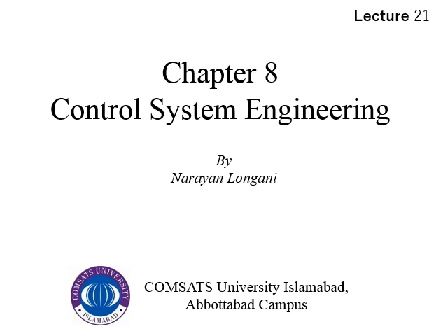In last class we started root locus. If we have a closed loop system which has an unknown parameter, and its transfer function, or in fact the characteristic equation defining poles of the closed loop system, depends on unknown parameter k, then we can't find closed loop pole location unless we know the value of the parameter. So root locus gave us a graphical representation of the path followed by closed loop system poles when an unknown parameter of the system is varied.